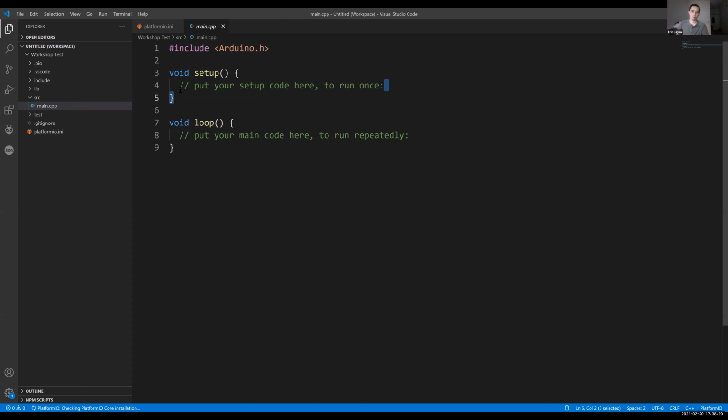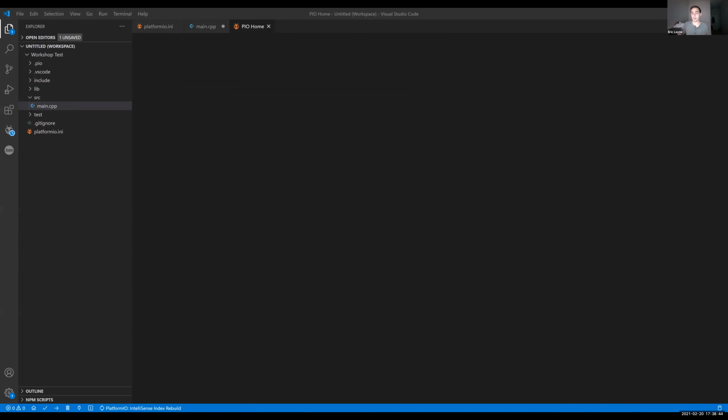The first thing we should do is determine what tasks we need. If we look at this, we probably want a communication task for the Raspberry Pi, one for the motor drivers, one for the IMU, and the buttons we can do as an interrupt, like I mentioned before. So just drag this over to this side.